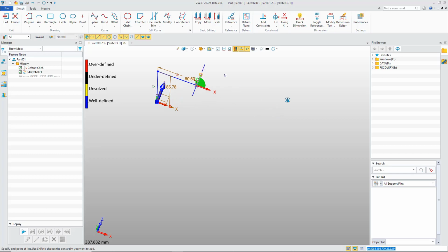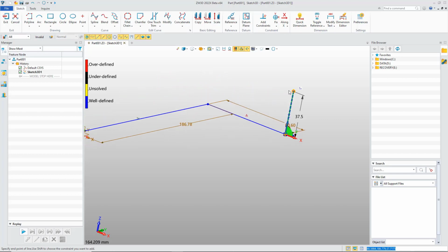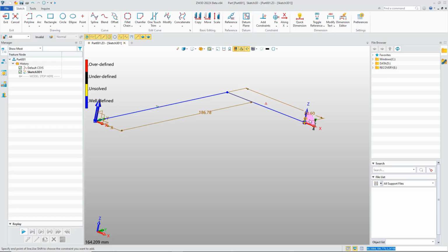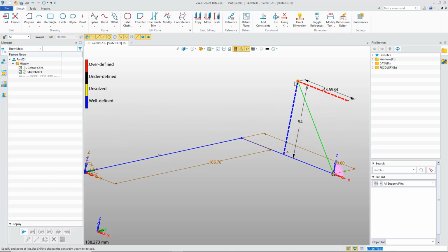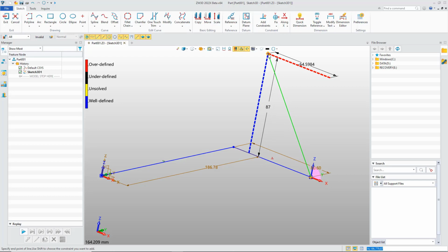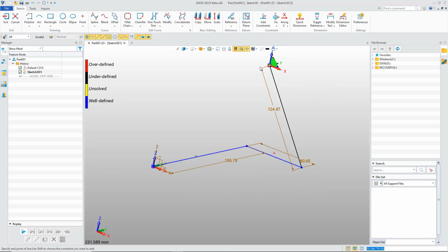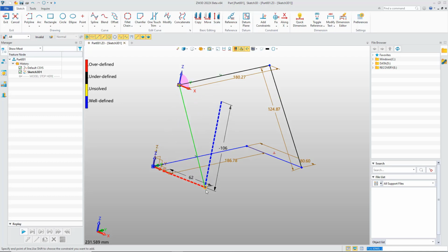And as I mentioned, if you want to draw the line to the required datum, you can select the datum first, and then you can draw the line. Also, for the remaining part, we use the same method. And select the XZ datum to create another line.